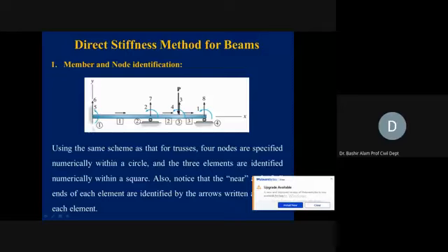At 1, it is a fixed support now, so it is restraining the rotation as well as the vertical translation also. 5 and 6, then at 2, the vertical displacement is restrained now, so it is 7, and then at 4, the vertical displacement, it is our 8. So it is an 8 degrees kinematically indeterminate problem if we remove the support conditions.